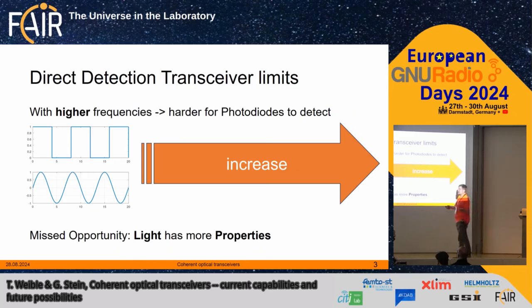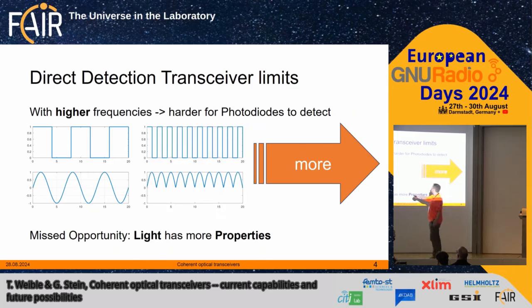But of course, you're also hitting limits. Let me show what it is, because if we increase the frequency, like increasing the steps, and we want the photodiode to detect our signal, we have to change our threshold. Now you see here we have -1 and 1, so that is the threshold you could put to describe my 1 and my 0. Now I have to change it.